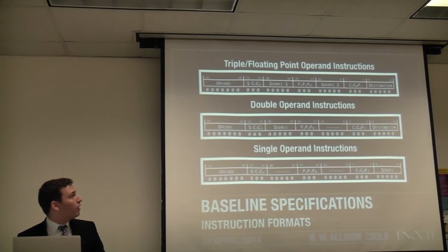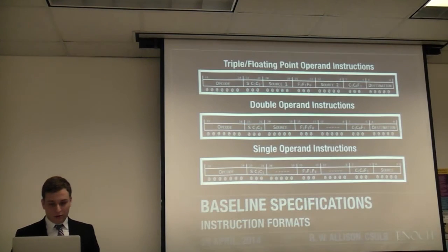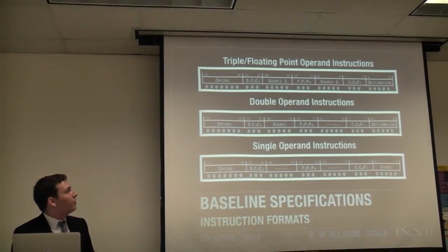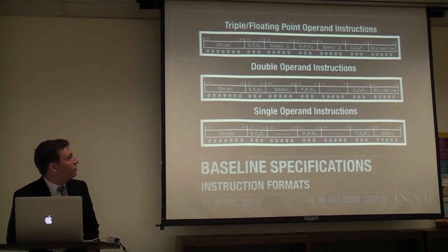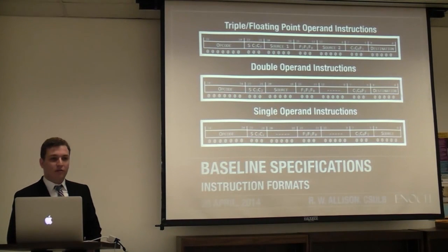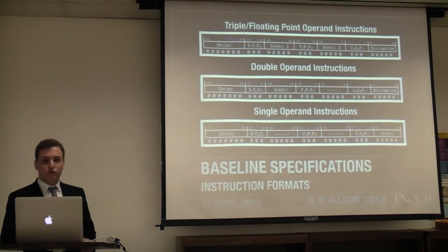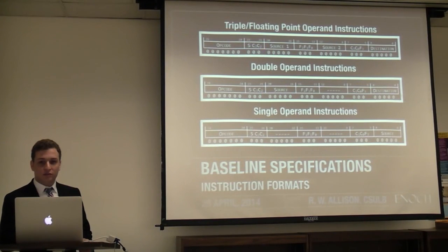And here are our opcodes, or our instruction formats. So in our enhancements, we added new fields. There's an S bit, which is for suppression of flags, so you can, we'll go over it later, but it's conditional setting of flags. And execution of instructions, too. The C is for choosing conditional execution of instructions, and the Fs, as of now, are unimplemented.